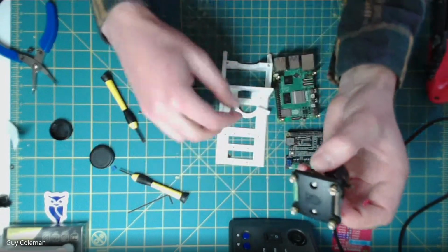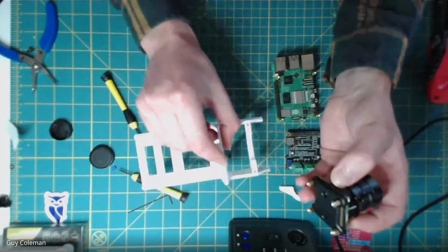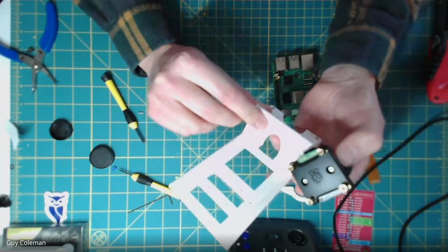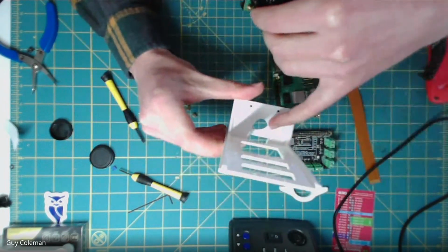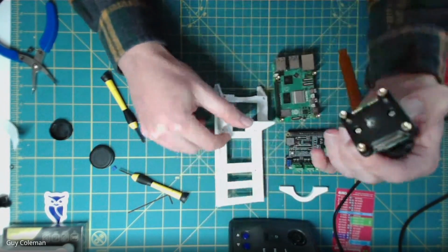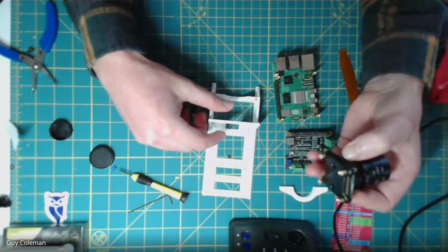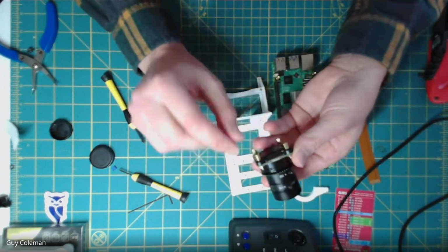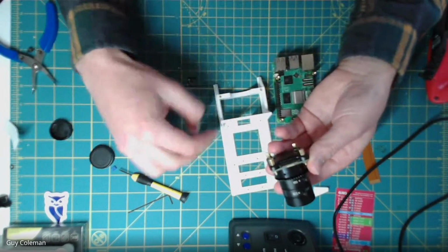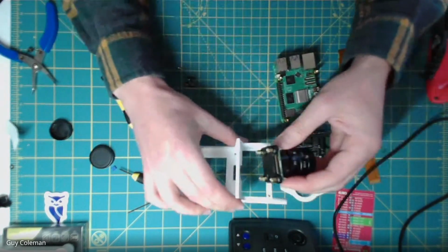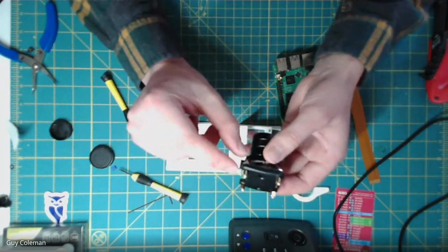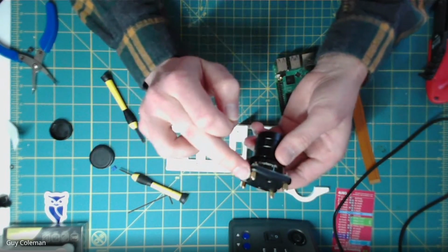Now, to mount it to the tray, you want to mount the camera first. I've made the mistake of mounting the Raspberry Pi first many times, but you do need to access these two holes down here to lock it in place, which will be obscured once you have the Pi in place. So you want to put the side with the camera cable facing upwards, and then just sit it in that tray like this. I should mention, sorry, I have also already added these standoffs.